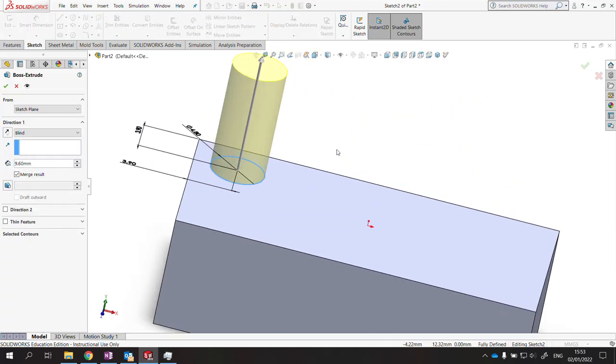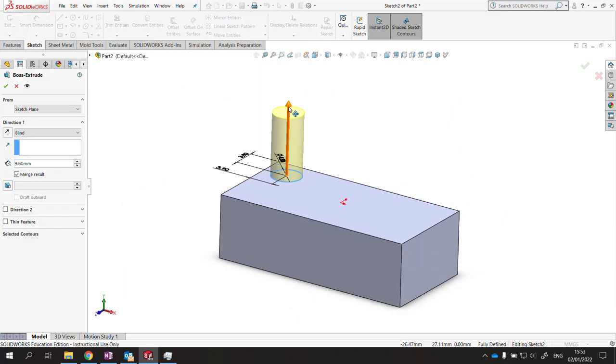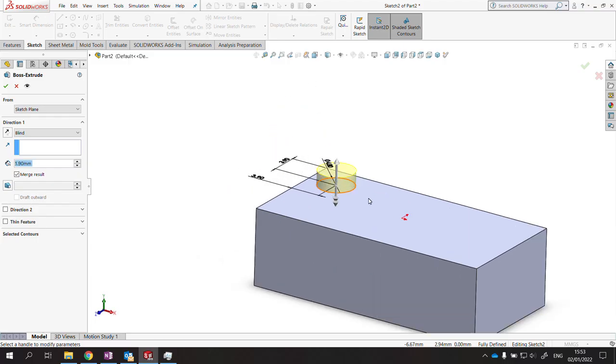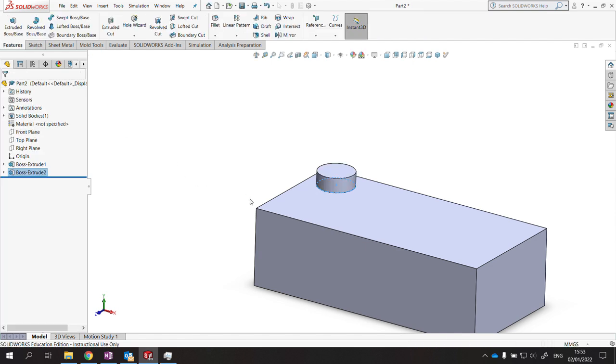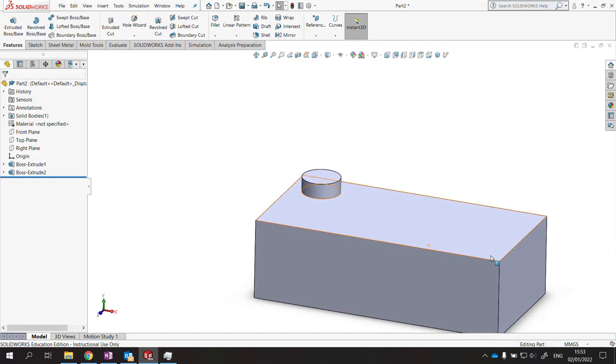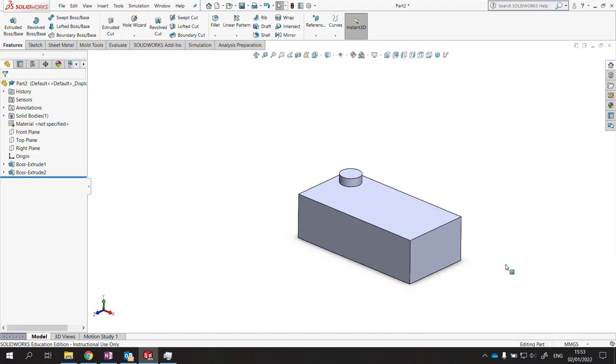Rotate it around. We've got a little arrow again. It's showing roughly what it wants us to do. And I know that I want this to be 1.8 millimeters. It doesn't have to be exact, but if you do it like I am, you'll get an identical model to a genuine Lego brick. Here we go, and that is the start of our CAD model.